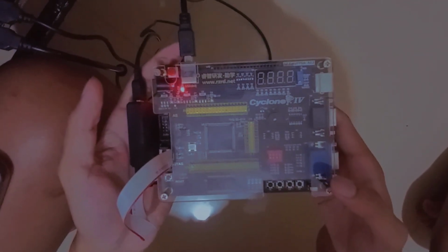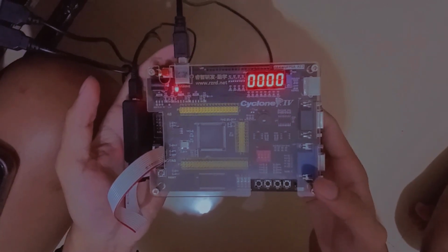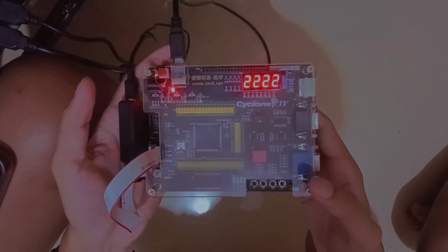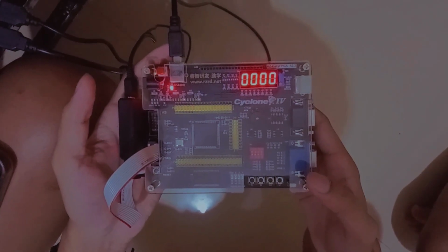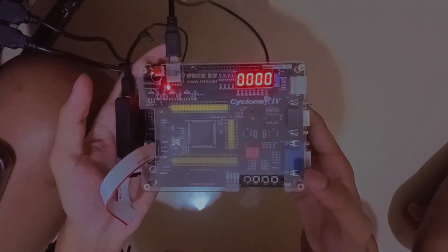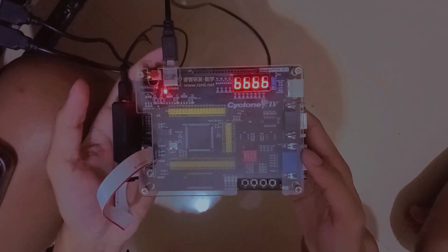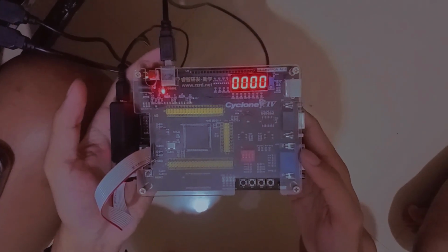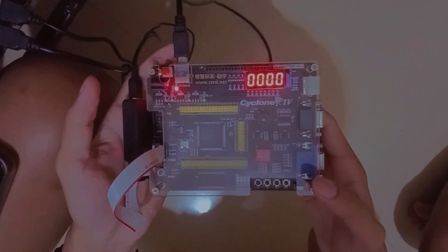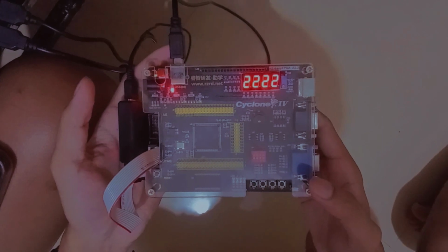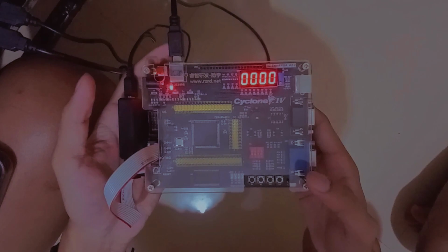The digit selection logic determines which digit of the 7-segment display is enabled. The dig register controls the digit selection pins of the display. The count register acts as a counter that increments by 1 on each clock cycle. The display data logic sets the value of the display data register based on the counter value. Finally, the 7-segment display logic maps the value of display data to the appropriate segments to display the desired digit or character. The seg register holds the value to be outputted to the 7-segment display.